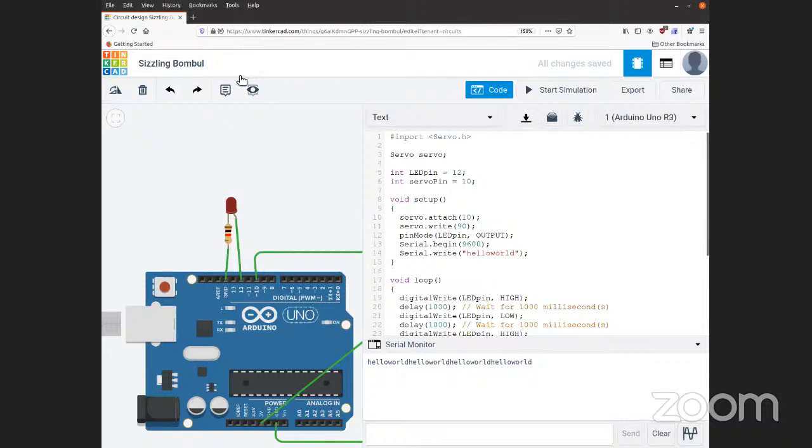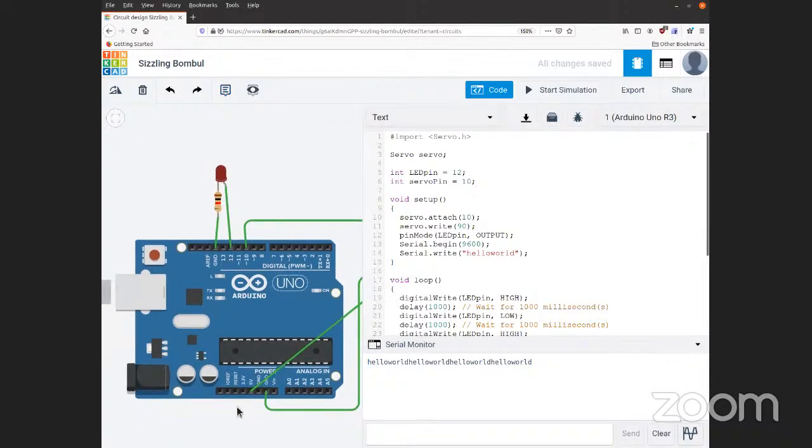I believe they are 5 volts. 5 volts, okay. And you have your little singular 3.3 down at the bottom. That'll be important because you will get extra parts that hang off of the Arduino. There aren't just what we call passive parts like resistors and so on. You will get a wireless board, and I'm not sure what voltage it connects to, but some of them will only work at 3.3 volts. So you can't just plug it into a 5 volt output if it can't take that. You have to be a little careful to respect its specs.